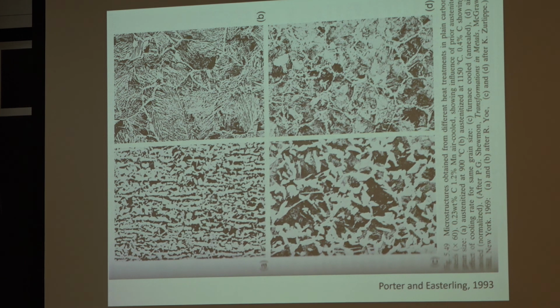So aluminum, when you quench, no strengthening. You heat it up, you get your strengthening. The steel is the opposite, where when you quench it, it goes into this relatively brittle phase. It goes to a martensitic transformation. That's the name of it. So it becomes from a cubic structure to a tetragonal structure, very hard to deform. And the goal with reheating is to gain back some of the ductility at the expense of a reduction of that yield strength. That's really how it works.